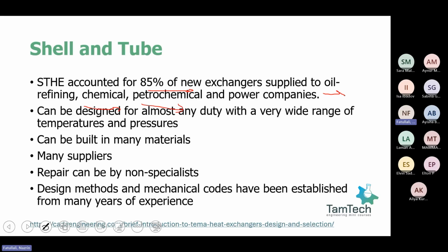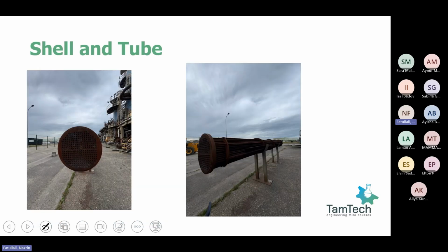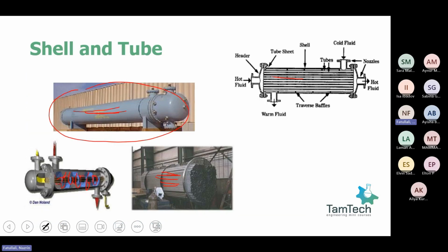The idea is pretty straightforward. Instead of one bigger tube, you have thousands of smaller, thinner tubes, all sitting in a large cylindrical shell. One fluid goes through the tubes, for example from there through these tubes and out. This is fluid in, this is out, and another fluid comes from the shell side from there and leaves from there.